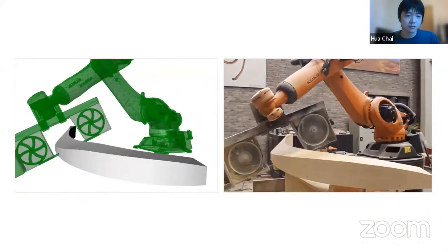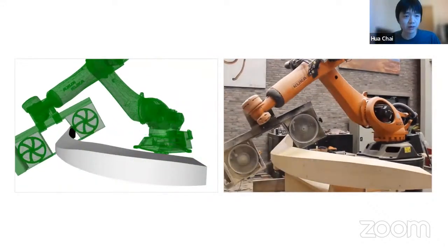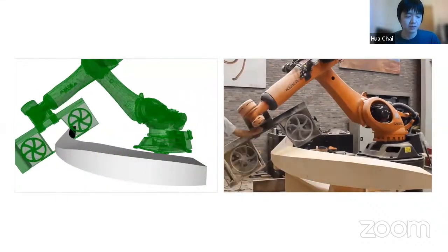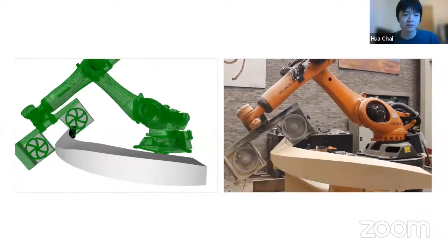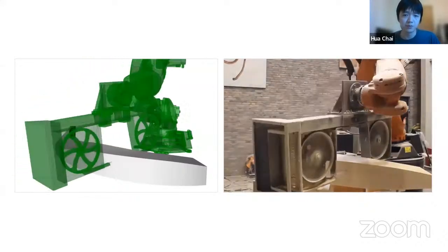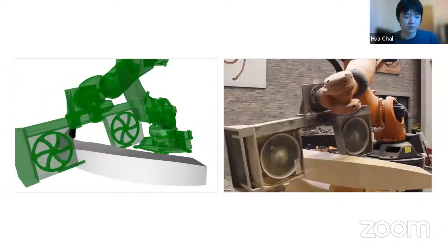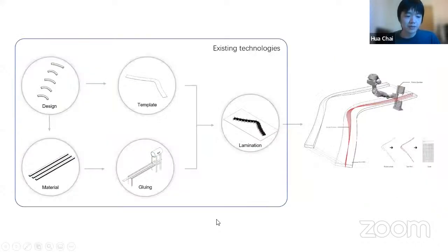And it works in a way similar to the hot wire cutting process, but it is more complicated because the bandsaw blade has a twist. It has to be parallel to the cutting surface all the time during the whole process. And also the bandsaw cutting process takes straight or single curved glue-lam with uniform sections as input.